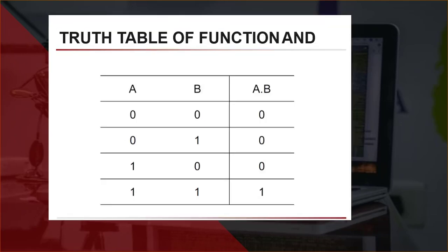Observe the truth table of the function, which performs a Boolean multiplication of the input variables, in this case the A and B keys. There are 4 possibilities, where only in the last condition, where we have 1 multiplied by 1, the output will be 1; in the others the output will be 0. Respecting the series electrical circuit from the previous example.